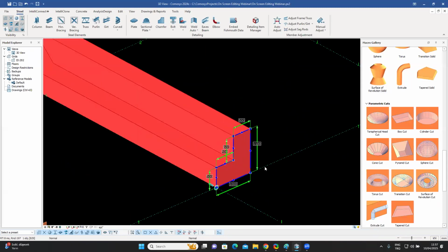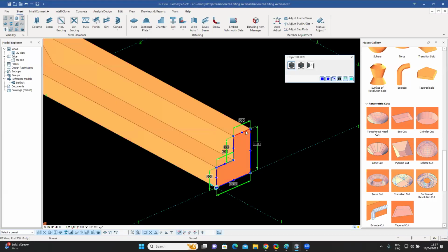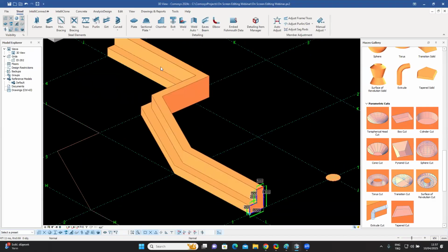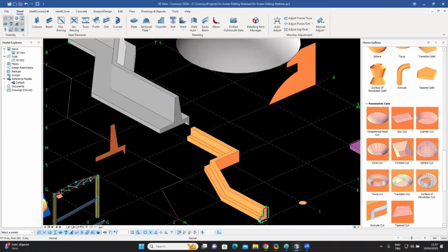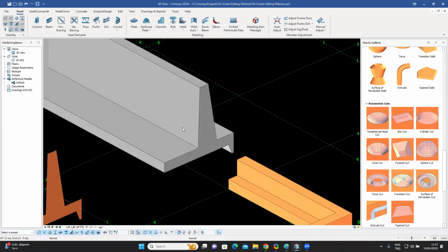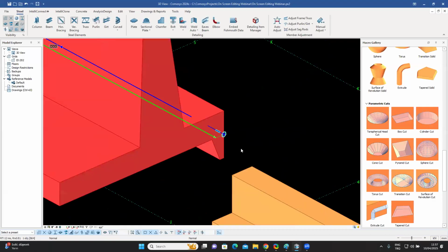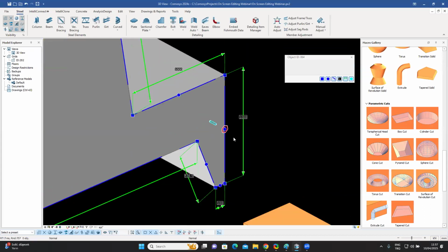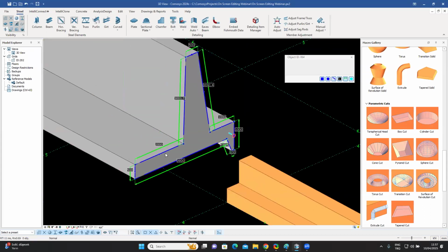And once you've created an extrusion, you can then modify it just like we did. So you have already created this extrusion, but then you can go in and say, I want to move it up. And when you move that little hub, the whole extrusion gets modified. This is very useful. For example, I've created a little kind of a retaining wall over here. See, this is basically the boundary which I used to extrude the retaining wall.